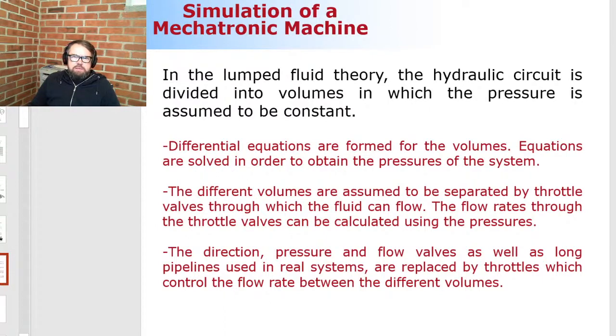All other components, like valves, direction valves, pressure valves, flow valves, each one of them will be modeled as a simple throttle. Simple throttles that may have a flow area that is a function of time. But that's roughly, in a nutshell, the modeling of hydraulics based on the lumped fluid theory.